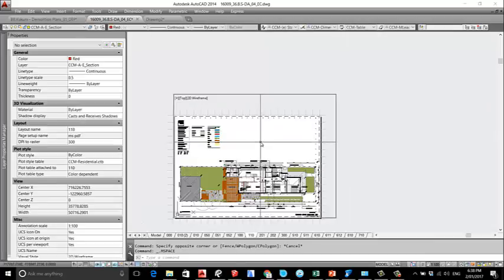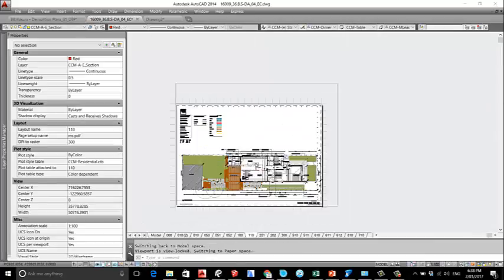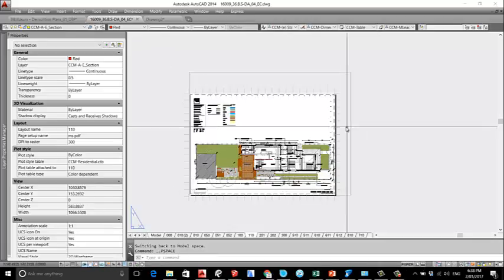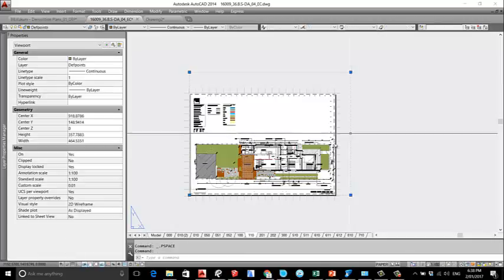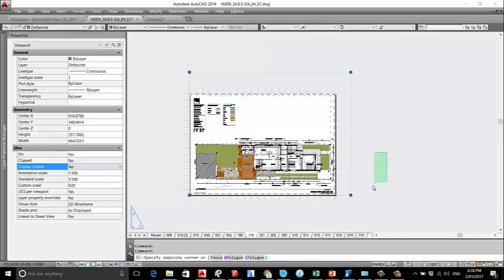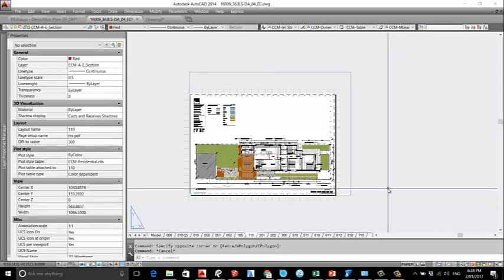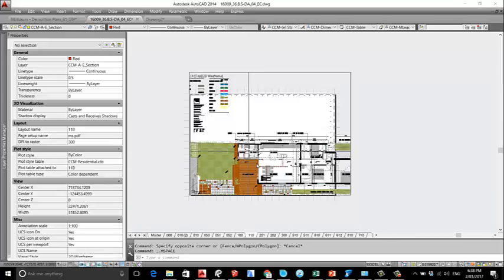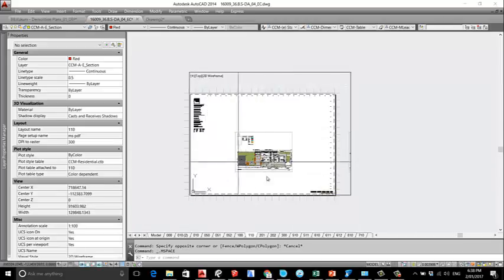So this is the viewport. I can then navigate. Oh, interesting. If I zoom, it doesn't go. Why? It's because the viewport is locked. So go outside, click on the viewport, and we have display locked. Yes. We say no. Now, I normally prefer everyone to lock the display once it's set up, because then, as you know, it gets really hard to navigate and get things back.